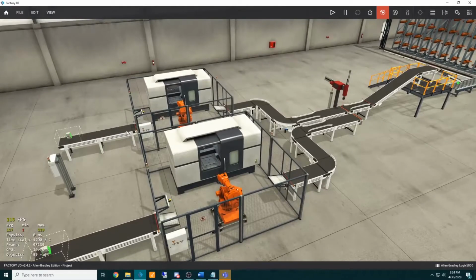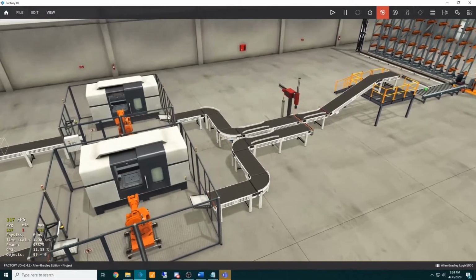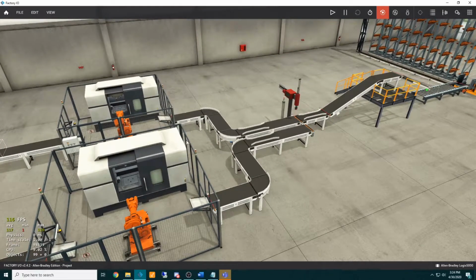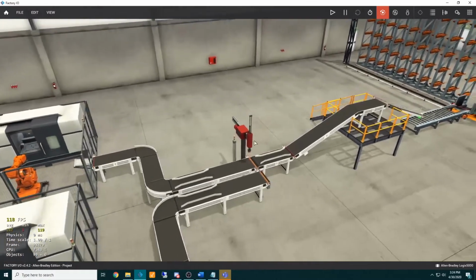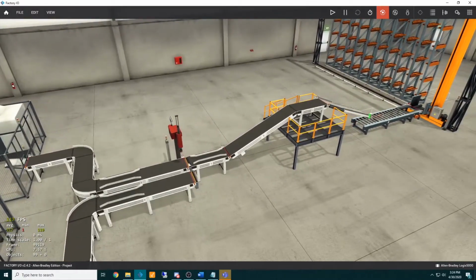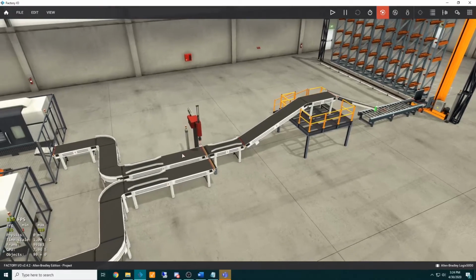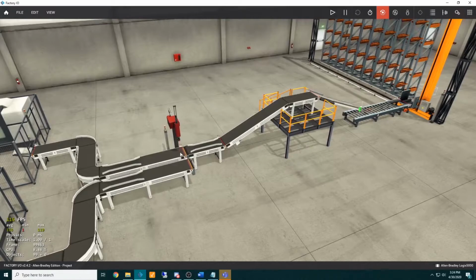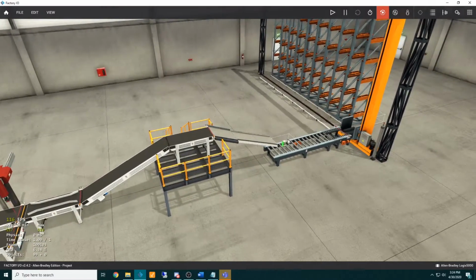The stop button will immediately stop the machining centers. If the part makes it past the machining center, it will go through the conveyors until it reaches the assembler. The assembler will immediately halt on the step it's on. However, if suction is on, it will remain on to keep the part on the end. If the part makes it past the assembler, it will go until it is put into the box.